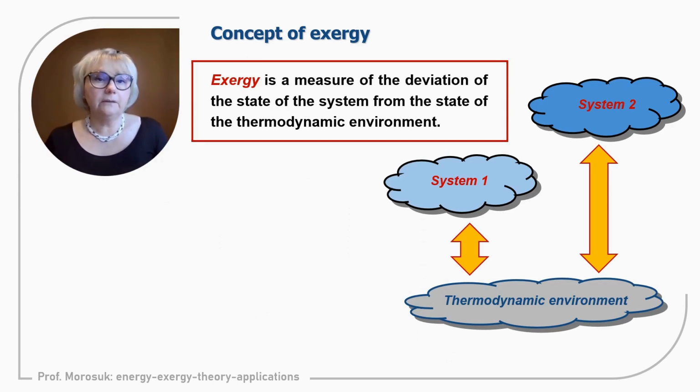Another statement or definition of exergy: exergy is the measure of the deviation of the state of the system from the state of the thermodynamic environment. So to define quality, we need to discuss how far we are from the thermodynamic environment. The further we are from the thermodynamic environment, the higher the quality.